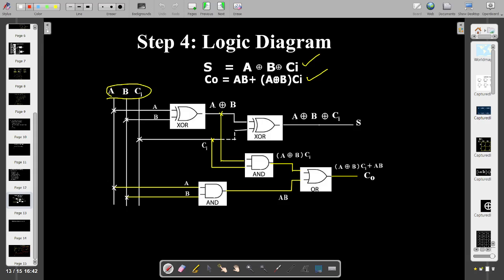If you check, it is clearly drawn here, right? XOR gate, A exclusive OR with B, so you got the first term. This is over. Again to combine with the CI using this XOR, the CI is taken and XORed. So you get this final output.